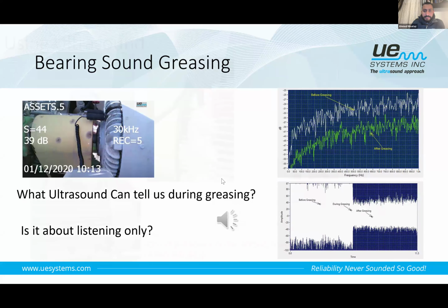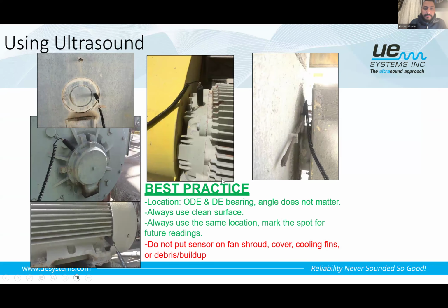So now the ultrasound technology helped me to listen to the friction level, to listen to these high frequency sound waves after converting them into low frequency waves, and helped me to listen to the friction level decrease during greasing the bearing and to listen to what's happening exactly inside while greasing the bearing.